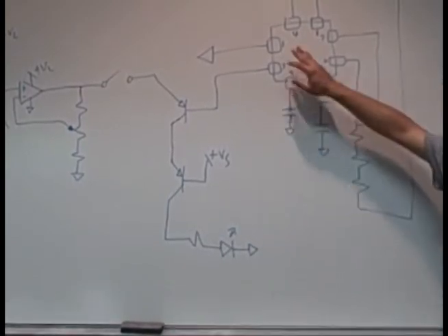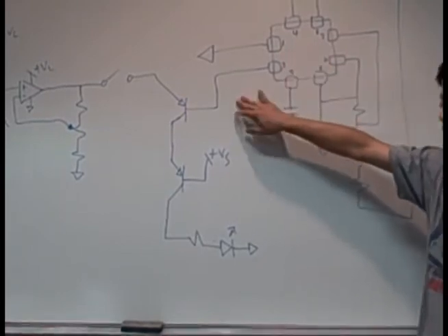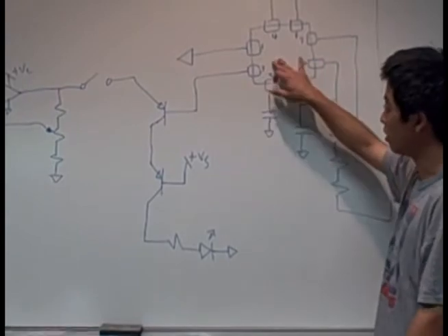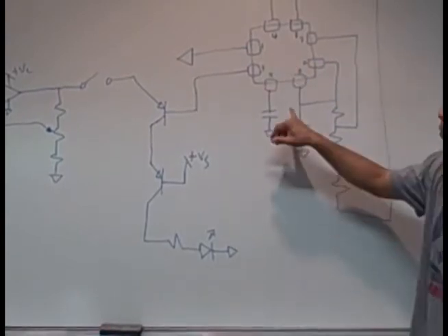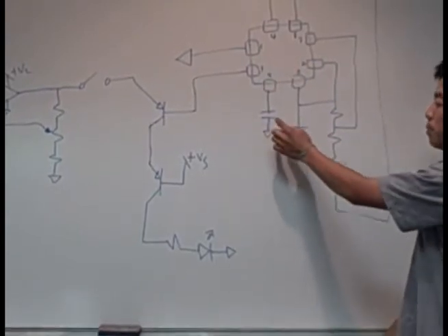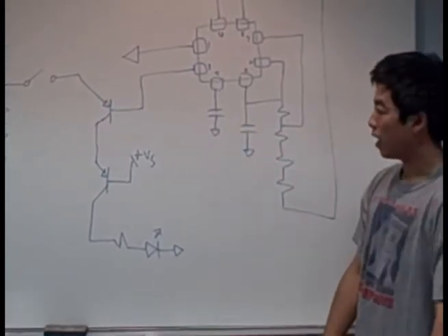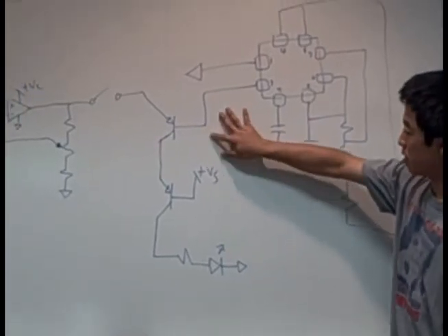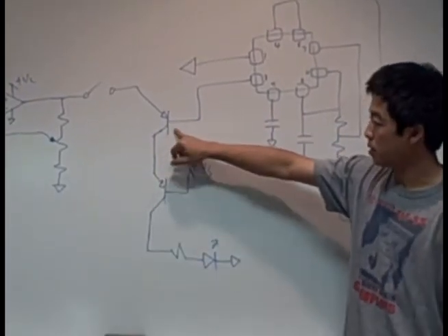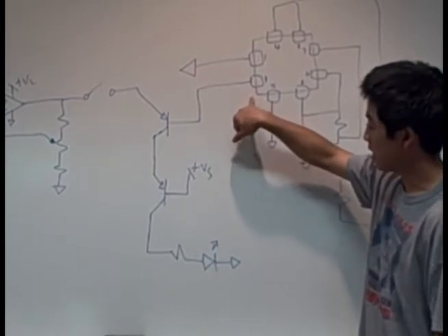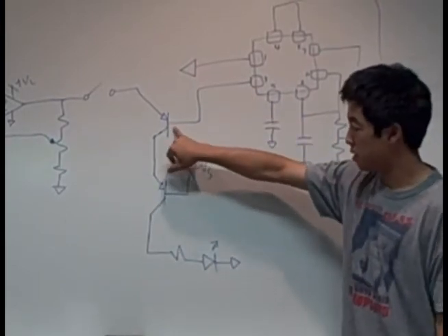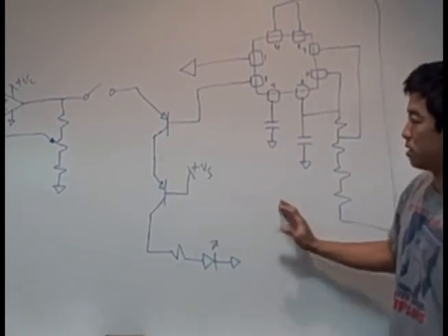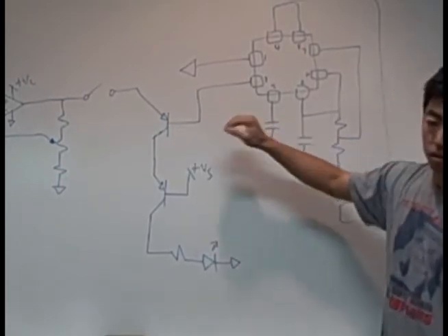So to start off, this timer chip outputs a high for 1 second and outputs a low for 0.1 seconds. This is achieved by calculating for these capacitor and resistor values and using an equation to do this. And this output is reversed by this PNP transistor, so that when this outputs a high, then this turns this transistor off, and when this outputs a low, it turns the transistor on. This was all mentioned earlier in the charge monitoring circuit.